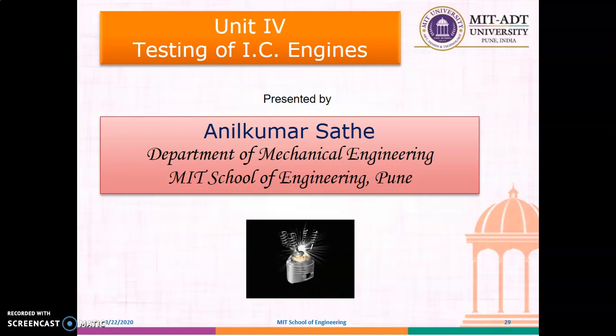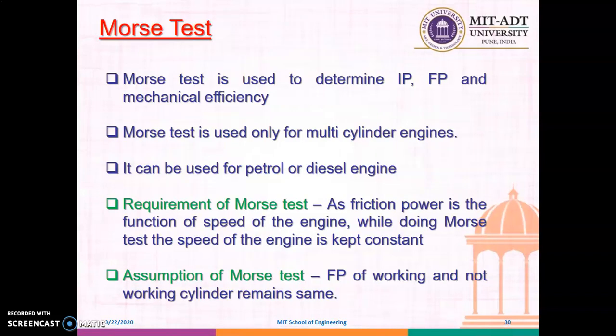Today in this lecture we are going to see some part of testing of IC engine, that is Morse test. Now why is this Morse test going to be performed on the IC engine? This is one of the trials on the IC engine to be conducted in the laboratory to determine indicated power, friction power and mechanical efficiency.